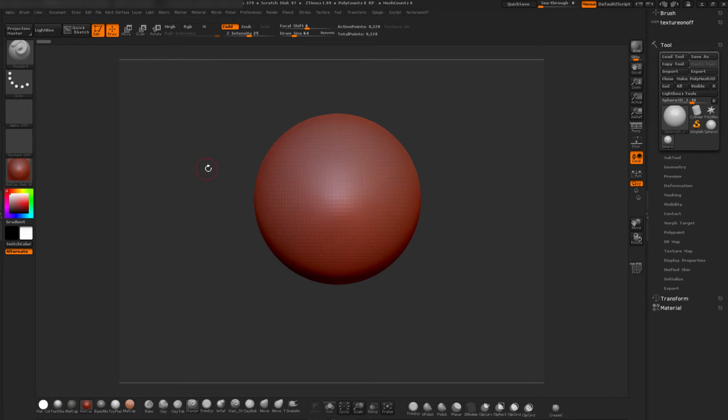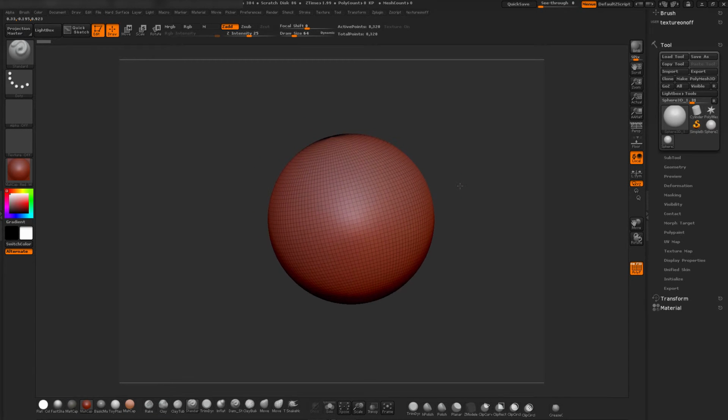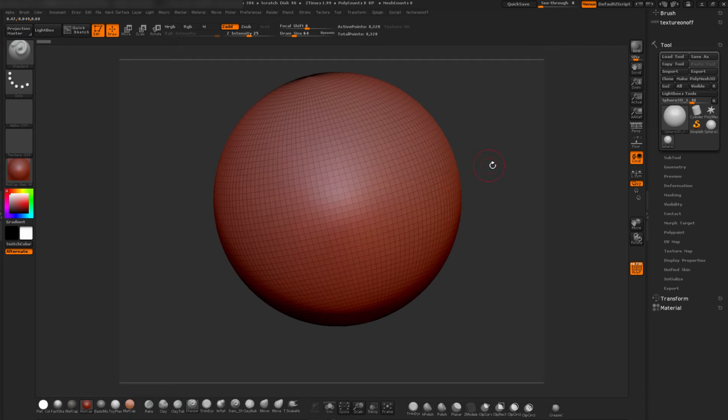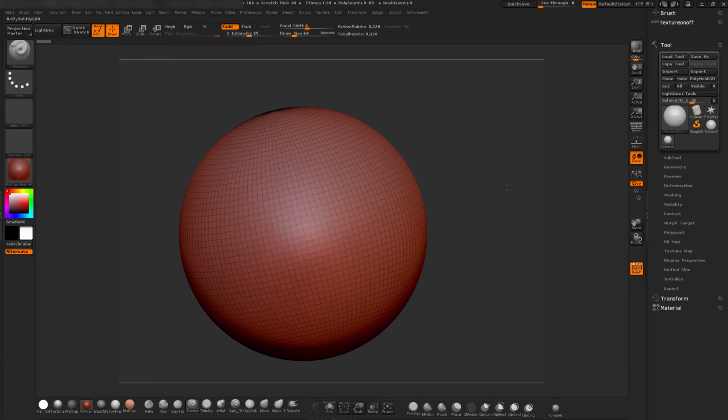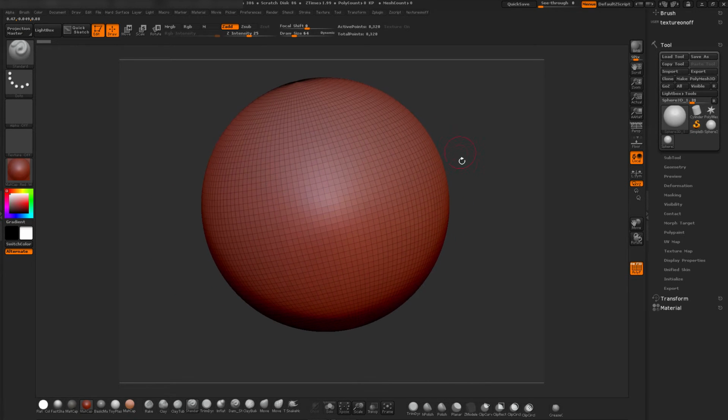Now we've gone into edit mode, we can actually go around our object. If I turn the poly frame on down here, you can see the object, and if we left mouse button we can click and go around the object. If we press the Alt key and left mouse button, you can translate it, and with the right hand mouse button you can translate as well.